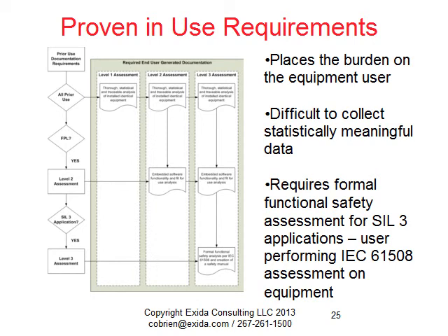So every application has to have statistical analysis. If it's got FPL, fixed programming language, then you've got to do a level 2 assessment where the embedded software functionality has to be analyzed and shown to be fit for use. And if it's a SIL 3 application, basically the standard says you've got to perform your own 61508 assessment.